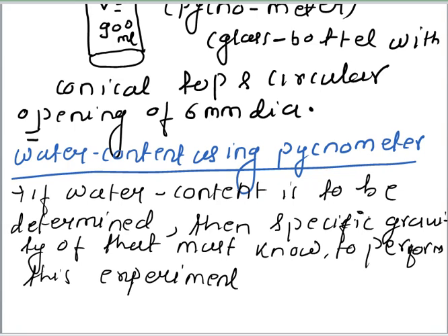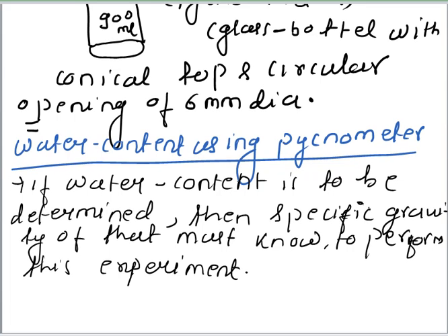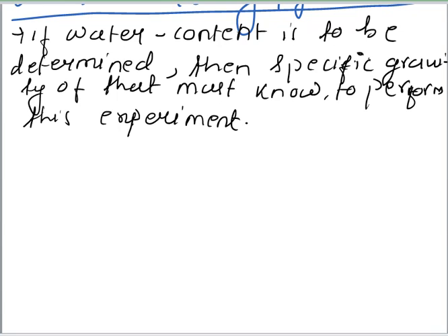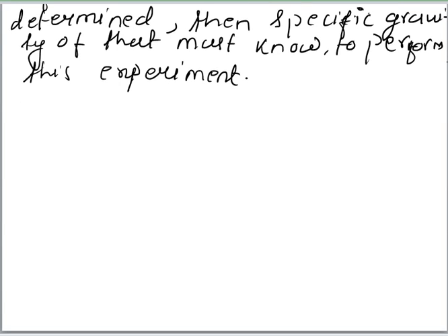Why it is required, I will tell you. You will see that without a known specific gravity we cannot determine the water content if we use the pycnometer bottle.